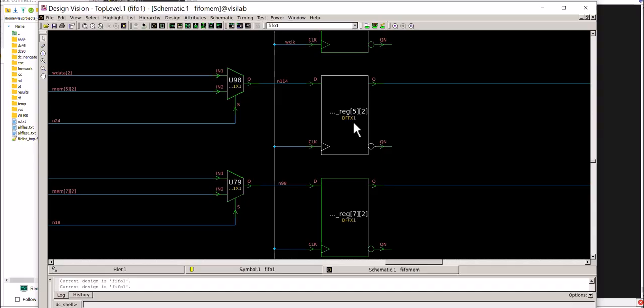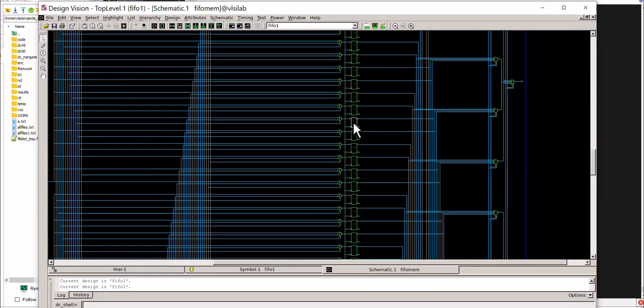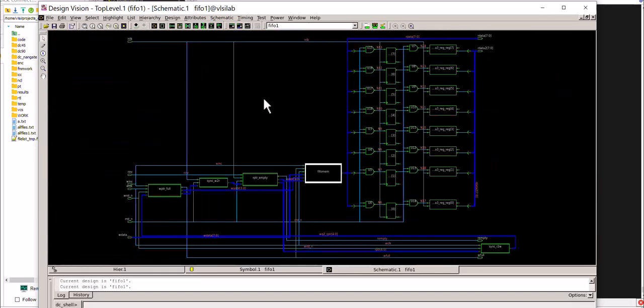So obviously there will be some timing constraint limitation here, because memory is implemented using flip-flops. Anyway, if you have any vendor-based model, you can plug that in there and define the vendor RAM.